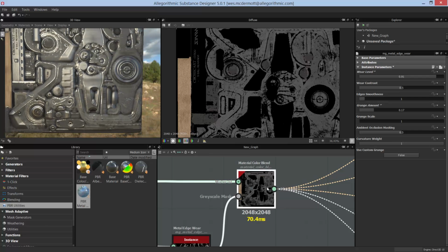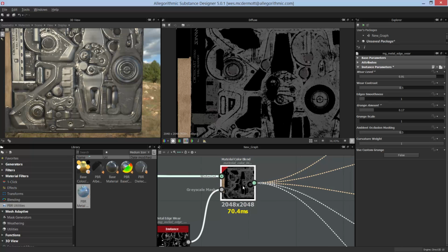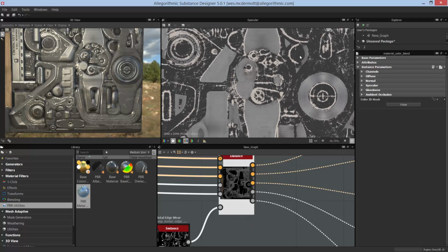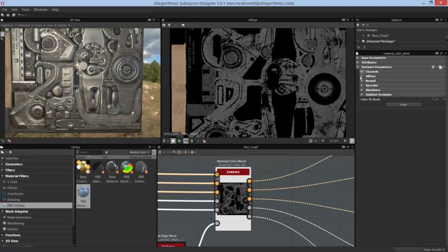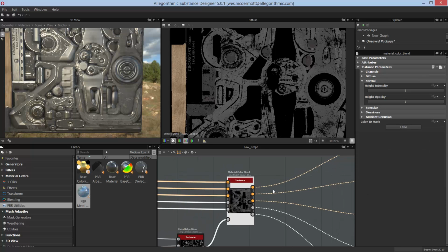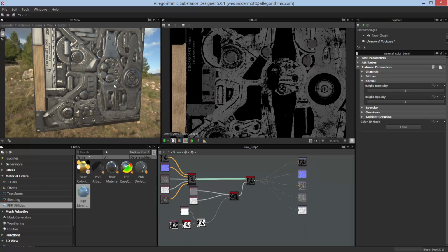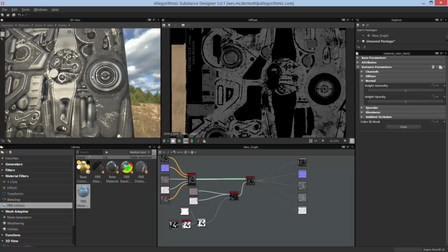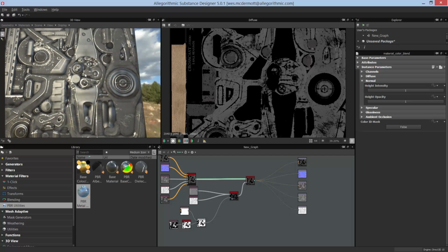And instead of having to take this effect and basically copy and paste it into each layer and all that stuff, Substance is handling this for me. So as I go through and change my settings, you can see all those settings already propagated to my specular and to my glossiness and so on. It does that based on how I told that effect to work with these individual channels. So at this point, we have that material color blend in place. We've further tweaked this asset, where we started with our traditional maps, we've converted those to PBR maps, and now we're starting to add some custom edge effects.